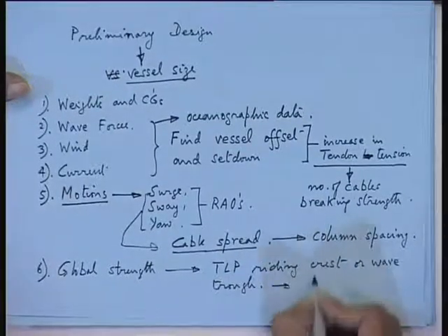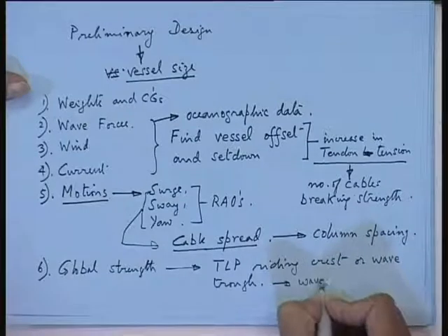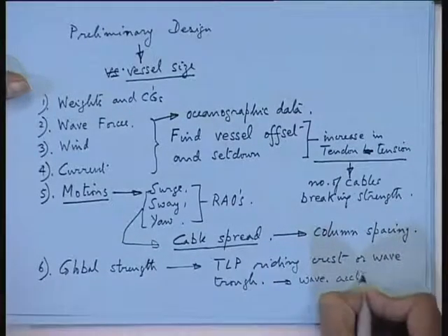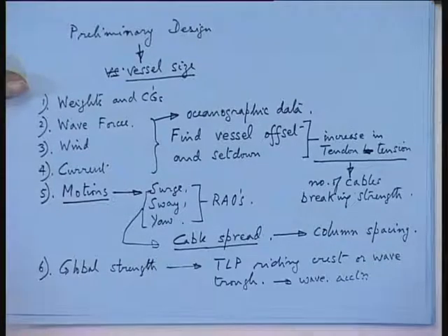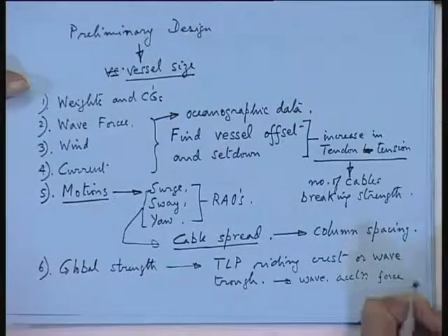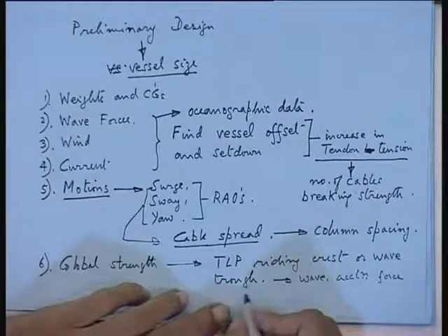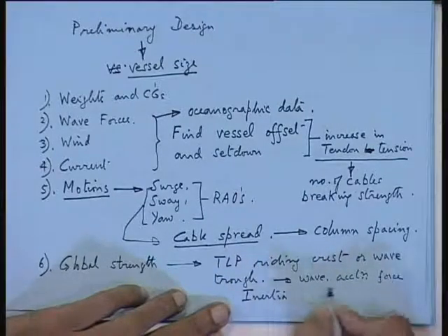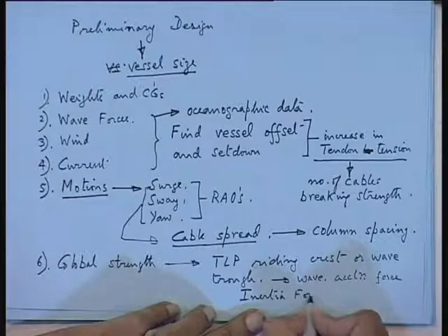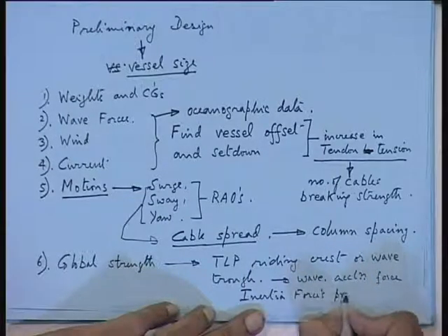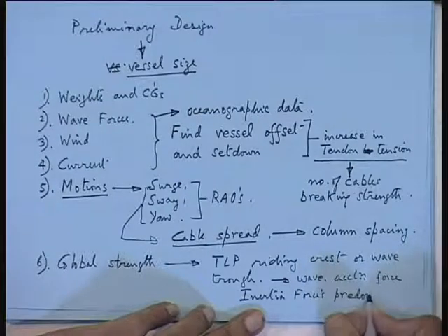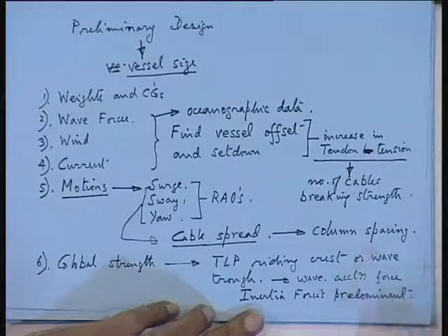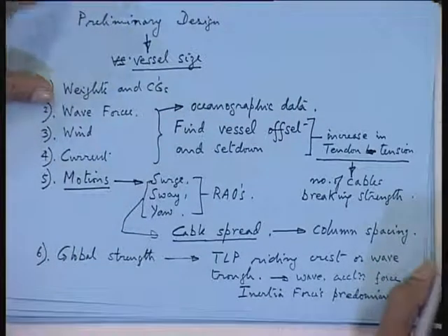So, here you calculate wave, mainly your acceleration, wave acceleration force. So, mostly you will find that inertia force is predominant. Inertia force is predominant in this sort of structure. Now, these have to be calculated. So, you will find a lot of hydrodynamic calculations you have to do besides the structural configuration. So, that ends your preliminary design.